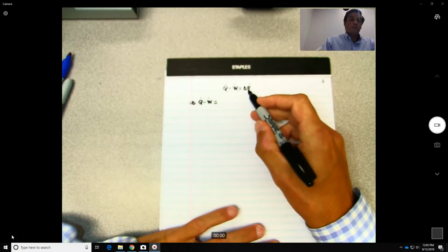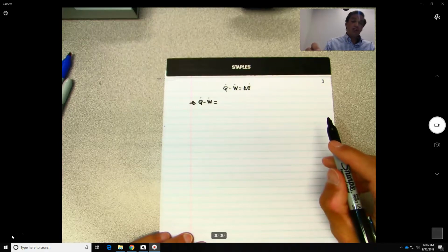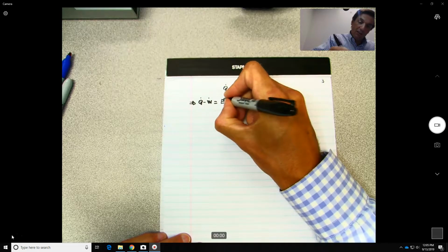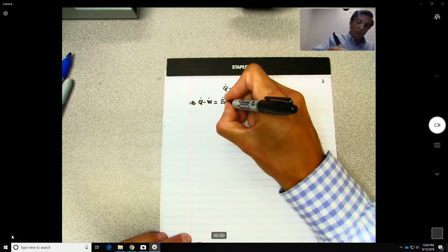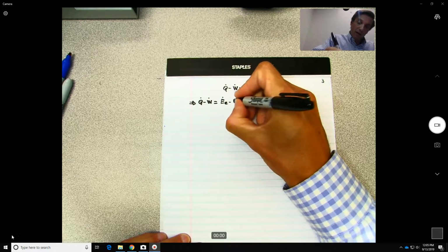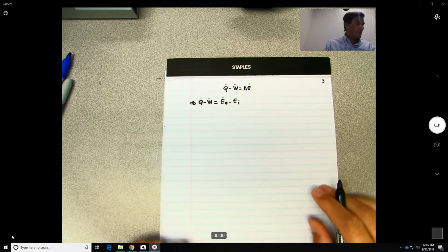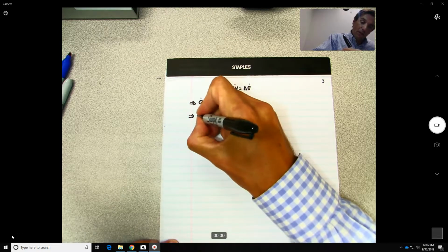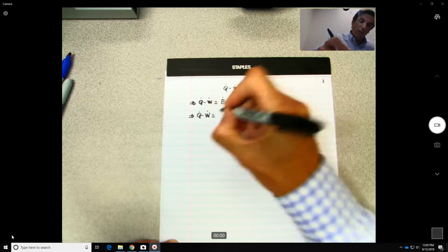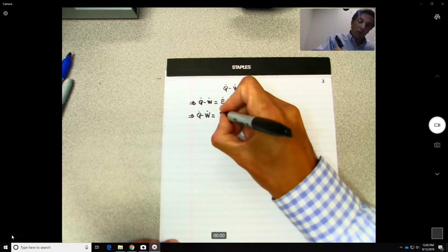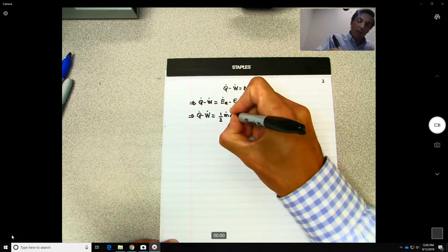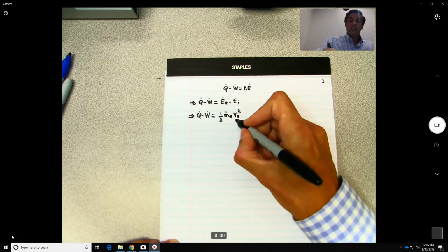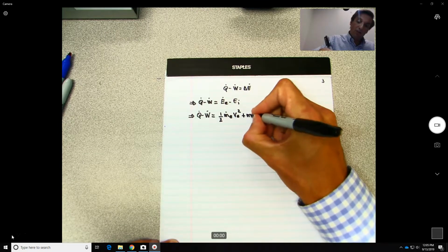So the energy can change as a function of what? The kinetic, potential, internal. So this will be equal to energy out or exit minus energy in. So this will give us what? Heat transfer minus power will be equal to, first the kinetic energy, 1/2 m dot exit V exit squared. So it will be the kinetic energy plus m dot g.